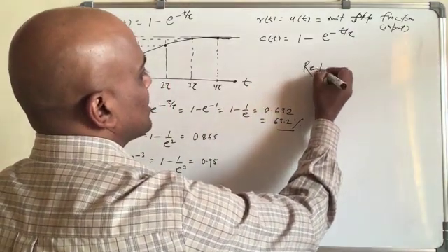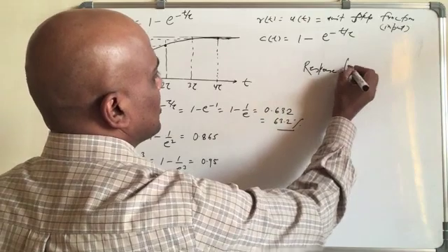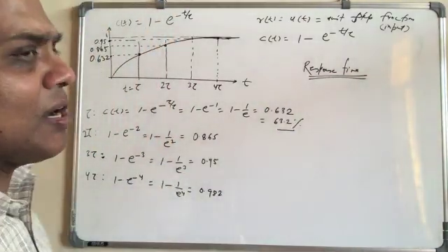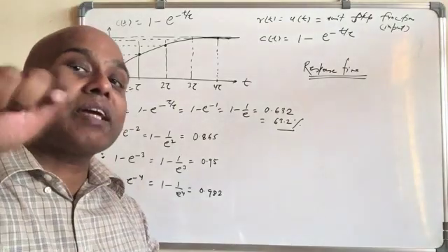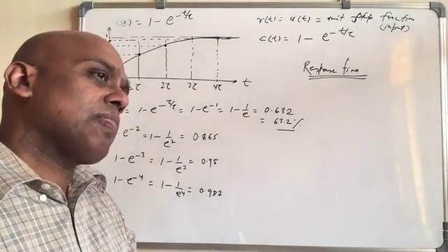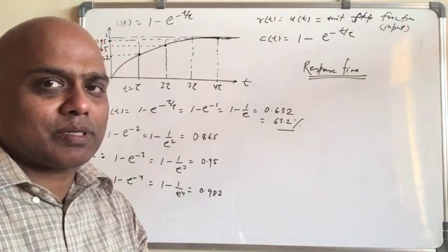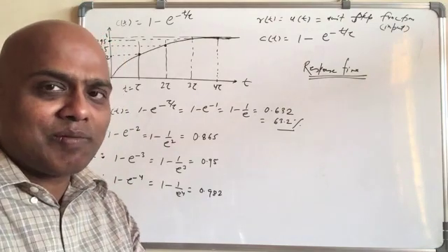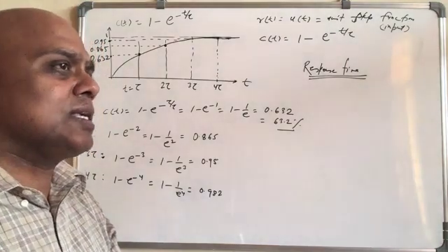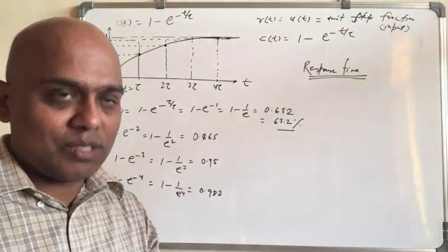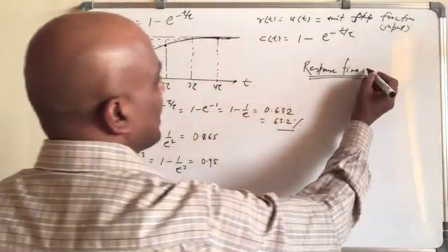So something called response time. Response time, meaning as in a control system, you change the reference, maybe like a step input. You have given the step input, you have increased or decreased, and you want the system to respond fast enough. So this tells you the response time.